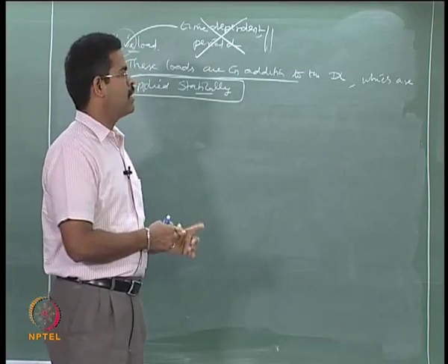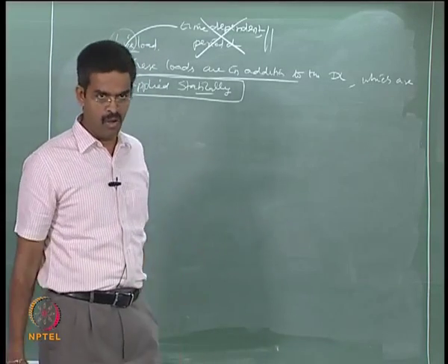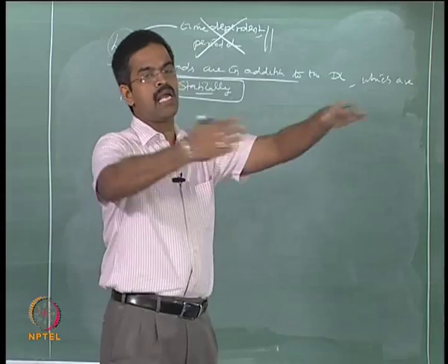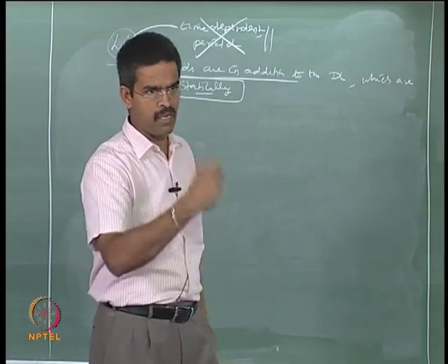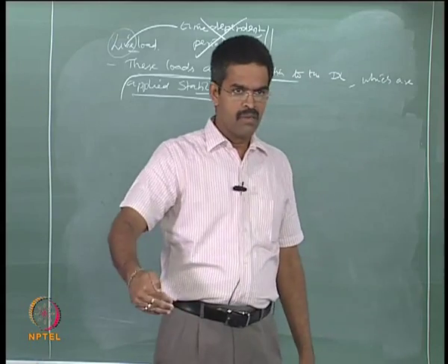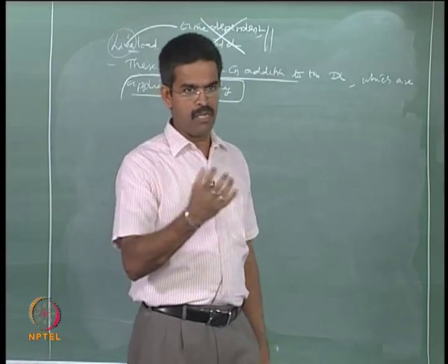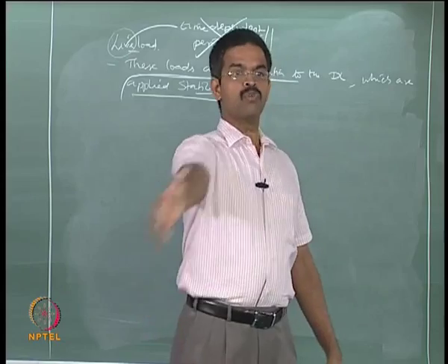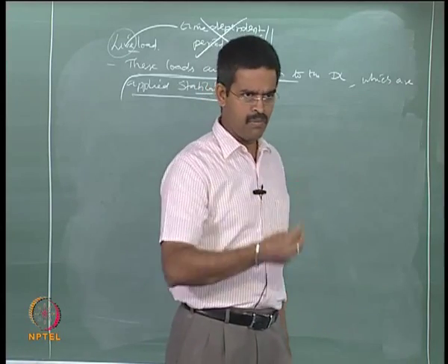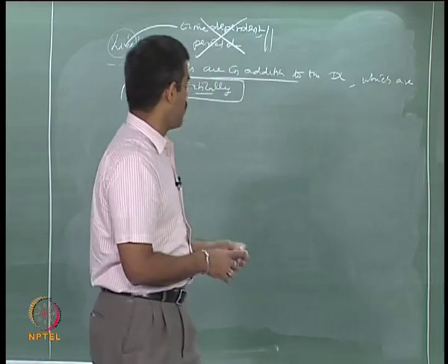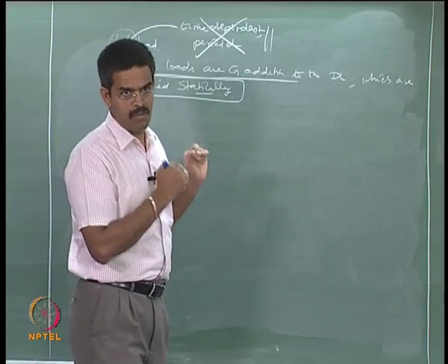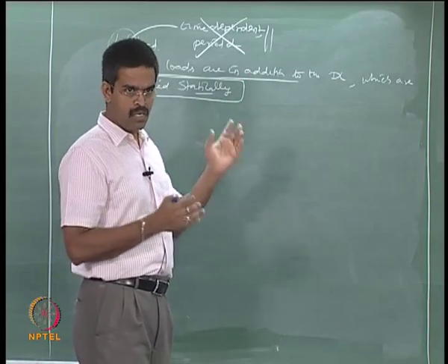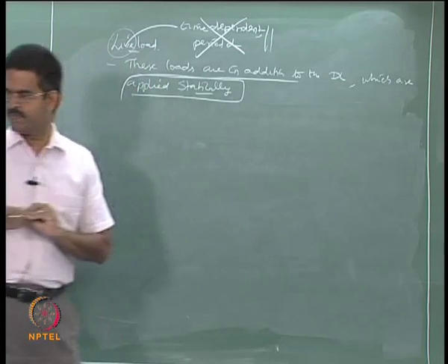We have a maximum of 50 to 75 people on board who will work, whereas the area is 100 meter by 100 meter. The TLP typically has a side of a square platform of about 75 to 90 meters. So, 10,000 square meters, only 50 people live. So, live load cannot be simply based upon the load from human beings. So, what are the sources of the live load coming on the structure in offshore or marine structures?